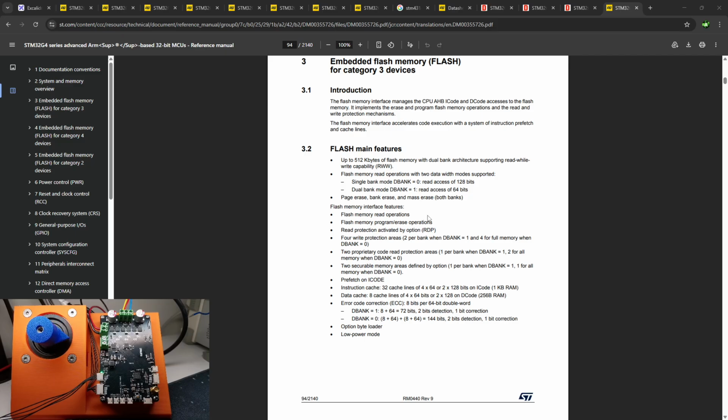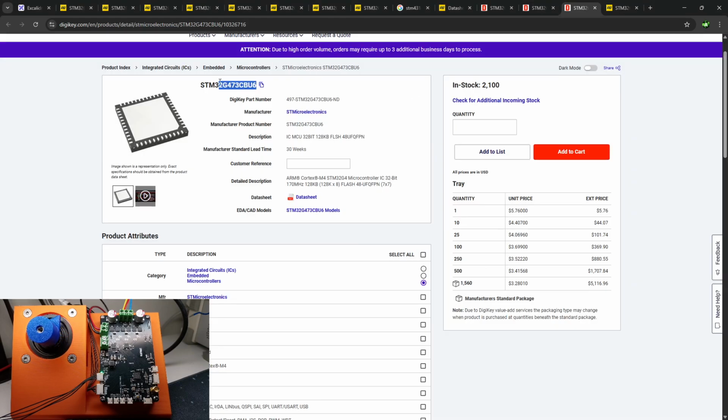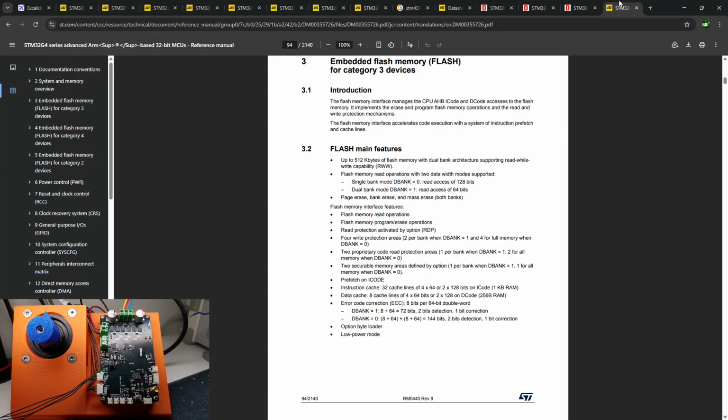The microcontroller with 5 ADCs, that is this one, in the same body, also has 2 flash pages, separate ones, and this is very useful. Very useful because in such configuration, you can write a bootloader very effectively. You can use one flash bank for your main firmware and one for the bootloader, and it's very easy to manage because you don't need to do too much hassle with your linker scripts.